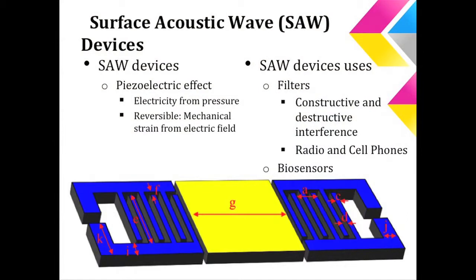So without the use of a clean room, the fabrication of surface acoustic wave devices, or SAW devices, would not nearly be as efficient. SAW devices function through the use of piezoelectricity, interdigital transducers, or IDTs, and surface acoustic waves. Piezoelectricity is caused by the stress and pressure of crystal. Not all material is piezoelectric. Only certain crystals like quartz are. Electrical impulses cause the crystal to contract and expand. And due to the contraction and expansion, mechanical energy in the form of waves is produced.